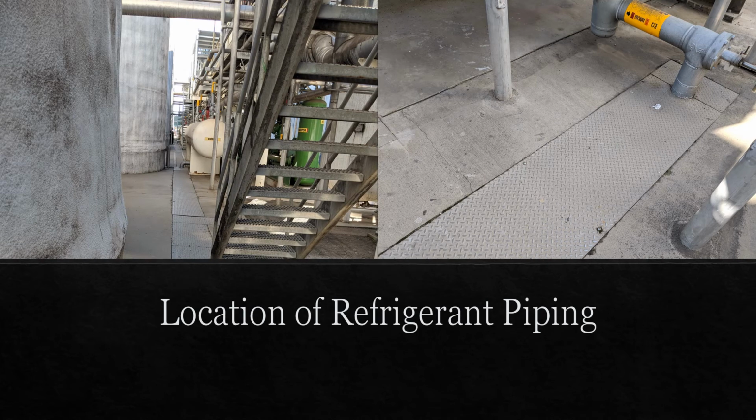The location of ammonia piping is restricted in Section 7.4.6. Piping must not obstruct a means of egress. Piping must not be placed in a shaft containing a moving object, such as an elevator. Piping must not be in a means of egress that is enclosed and accessible to the public. Piping can be installed underground so long as it is protected from corrosion. And finally, where piping is installed in concrete floors, it must be encased within a pipe duct.